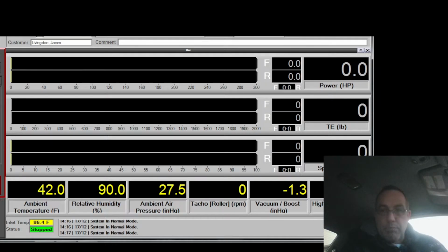So if I raise the boost, now the density of the material in that cylinder between the electrodes is much higher. Now I have more non-conductive molecules between the electrodes of my spark plug. And so if I don't have enough spark energy, is this flashing? Yes, it is. I don't have enough spark energy via the coil packs to strip those electrons off and make current flow through the air and insulators effectively, it won't. It'll misfire.